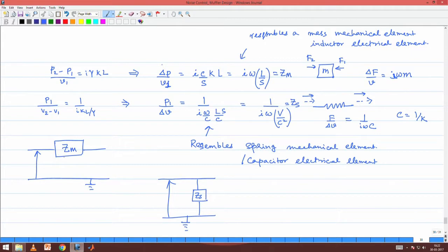So, you can as well delete this Zm and short it, right. So, the effect of Zm can be completely ignored, whereas the effect of Zs cannot be ignored, right. If I short the circuit here, then a lot of current will flow through this shunt path, and therefore the current that will flow through the other branch will be minimal, right.